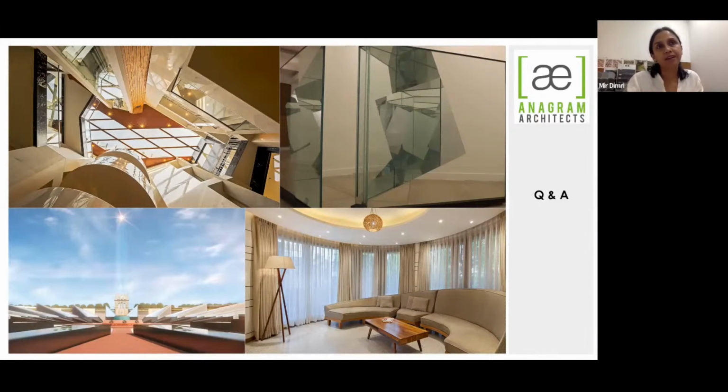So for example, in this top left picture, you see this curvilinear shiny surface. It's actually a railing around a circular staircase in the atrium. At one point we wanted to make the railing in complete glass. Now this railing is a winding strip that's turning in two directions at times. Curving glass in only one direction is one thing, but to have it curve in two directions is more challenging, and for whatever reason, time, ability, or cost constraints, we have not been able to do it.